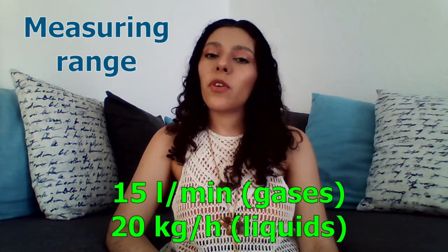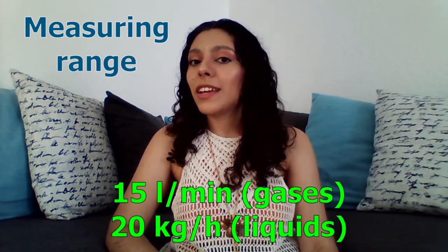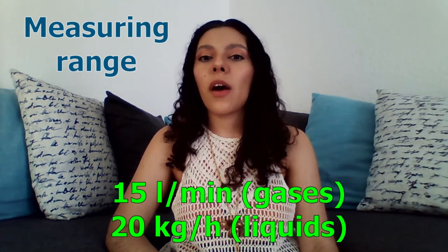The measure is suitable for low gas flow rates that vary according to the 0 to 10 cubic centimeters per minute models. To increase the measurable flow, the fluid is diverted with a capillary, and an inserted laminator guarantees the same laminar flow as in the capillary. As the relationship on sections between the laminator and the capillary is known, by measuring the flow at the sensor, the measurement of the total flow is obtained. Thus, measurable flow rates reach 15 liters per minute in gases and 20 kilograms per hour in liquids.